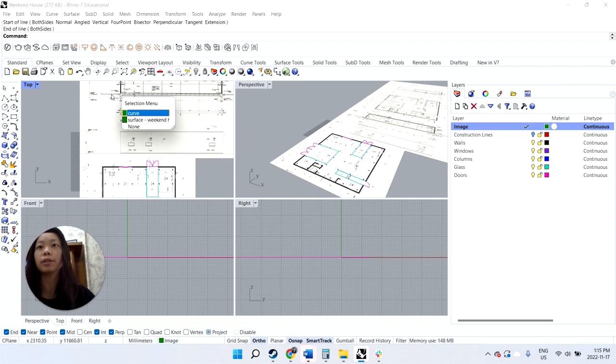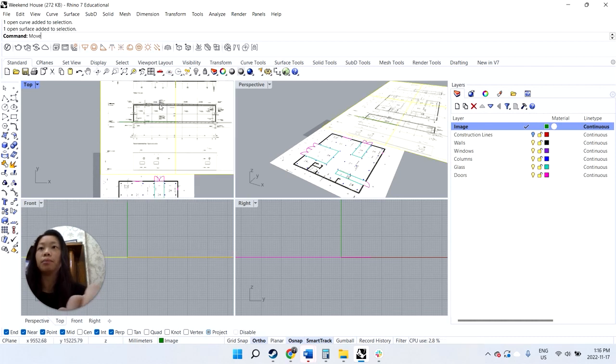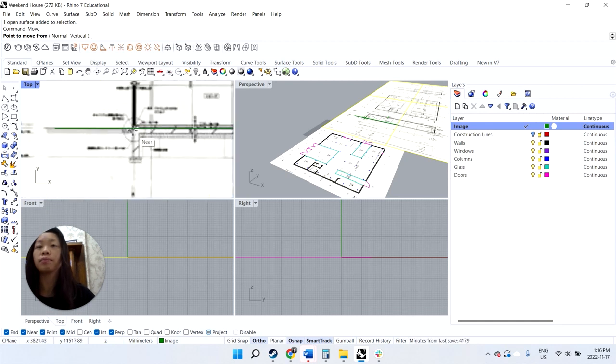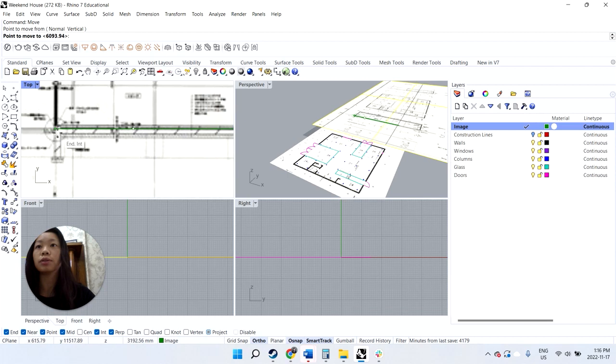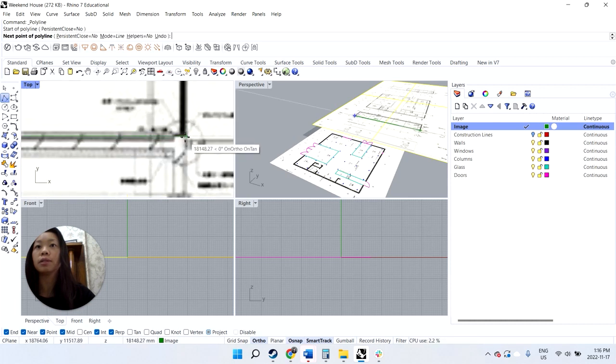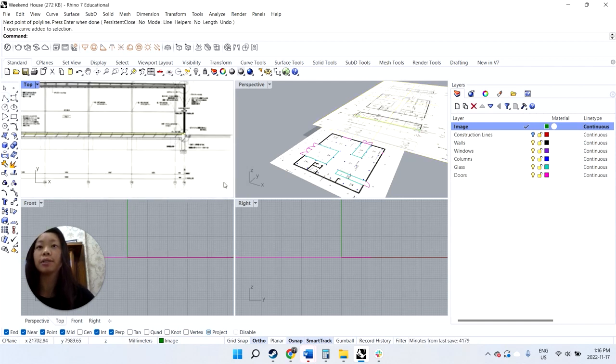and then I'll click there. So this is a line. This should be the full width of the building, right? Next, I will, let's say, type in move. Just going to move the section over to one corner. And then I'll draw another line, let's say from end to end in the most accurate way, or as close as possible, right? This is not going to be perfect.